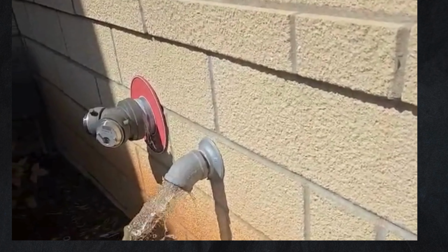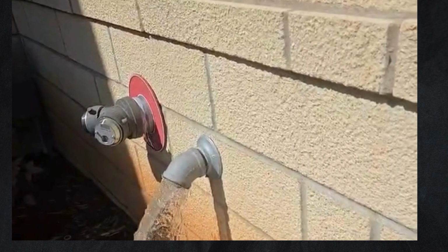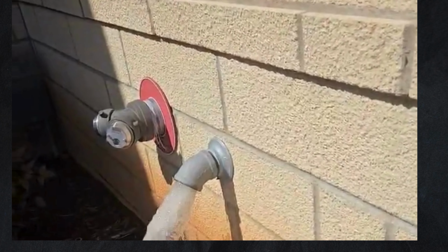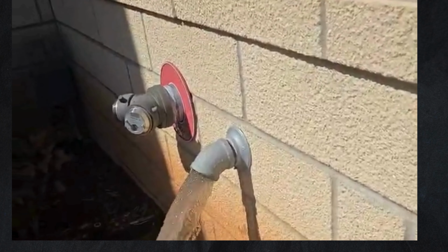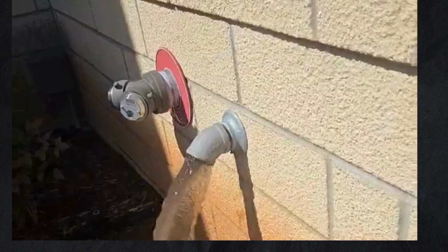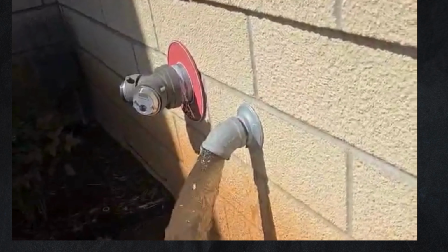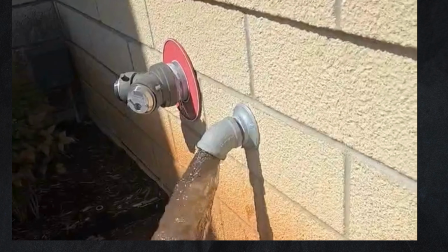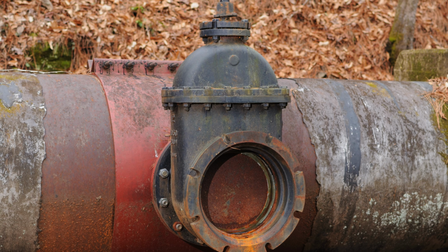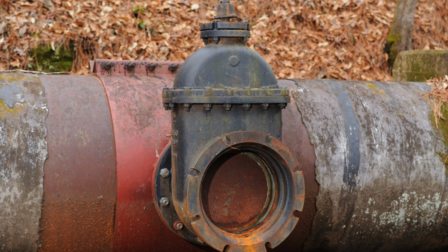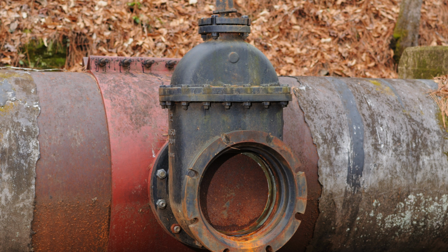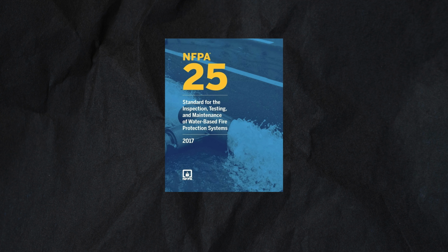After a new system is installed, a main drain test needs to be conducted. Why are main drain tests conducted? The common practice known as a 2-inch 50mm main drain test typically involves fully opening the 2-inch 50mm main drain until the pressure stabilizes. These tests are documented to identify any potential degradation of water supplies or to uncover closed valves within the overall water supply system. For newly installed systems, conducting a 2-inch 50mm drain test requires establishing a baseline measurement during the initial approval phase of acceptance testing. Additional guidance on conducting these tests can be found in NFPA 25.